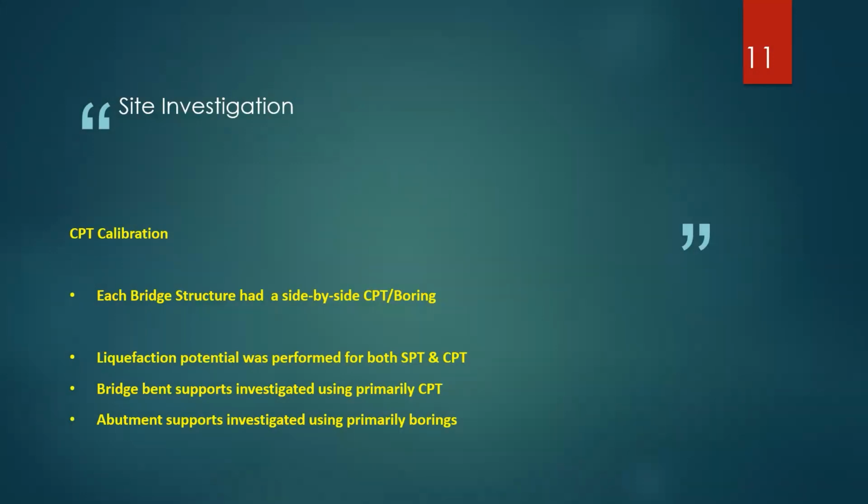So, the CPT calibration. In every job, you need to have your CPT calibrated, right? So this was no exception. We wanted to make sure that we did that. But by that, I also mean we required in the technical provisions that for each bridge structure, you have at least one side-by-side CPT next to the boring. The reason we did that is because we want to get the data on CPT next to the boring to see how they calibrate against each other for the site-specific aspects of the boring.